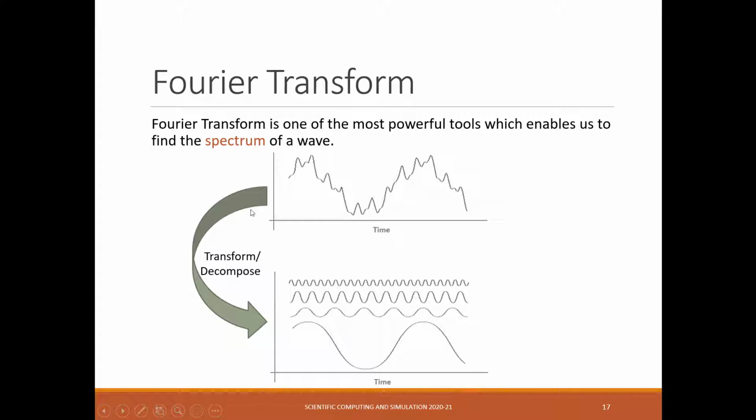As we can see here, the original signal is decomposed into 4 signals. Each represents a tone or a specific frequency in the musical signal. In fact, using Fourier transform, we can recognize the original signal is made up of 4 different frequencies.